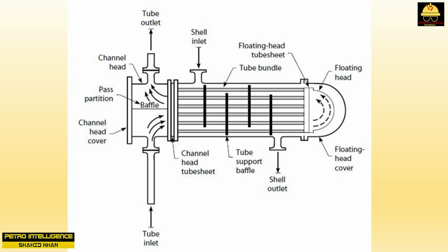The tube side fluid now flows into the floating head, which acts as a return header for the tubes. The tube side flow makes a 180 degree turn and flows back through the top half of the floating head tube sheet. The floating head is firmly attached to the floating head tube sheet. But why is it that one end of the tubes must be left free to float? The reason is thermal expansion, or, more precisely, the differential rate of thermal expansion between the tubes and the shell.